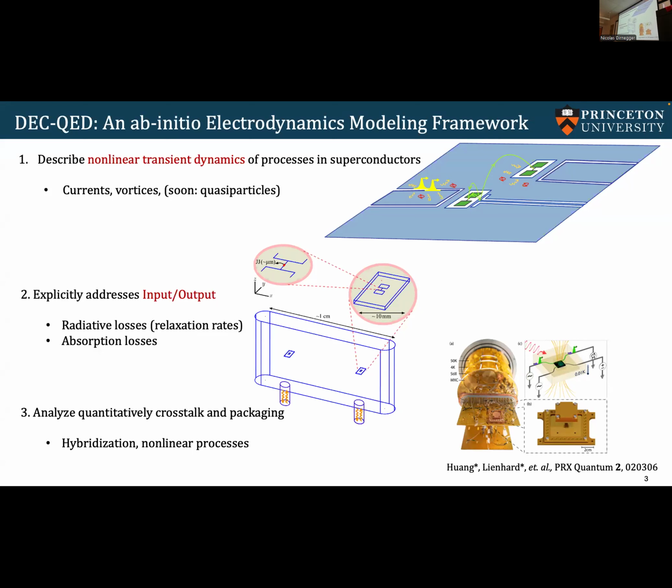Even though there has been a lot of development on theoretical approaches and tools, with some very successful techniques, many of which we've learned in this workshop, for example AWS Palace or ANSYS HFSS for classical E&M simulations, PyEPR, a classical-quantum hybrid analysis tool, and SC-qubits from Jens for circuit-level quantization analysis, we already see a general strategy or workflow for modeling and designing superconducting circuits from classical E&M to quantization.